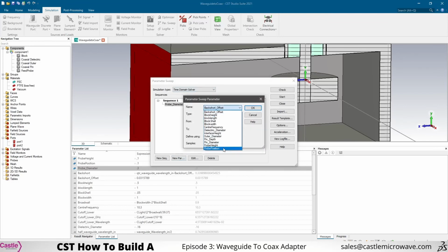And then we'll also add the probe height, so where it's starting. Sorry, no, rather, the probe height is the total height of it. So this needs to have at least some height, so we'll start at 0.01. We're not sure yet, it might want to be the entire height of the probe, so we'll go to 0.2. We'll make this 5 samples. And then probe position, we could start it at the very top, we could start at the very bottom. And then we'll use 5 again.